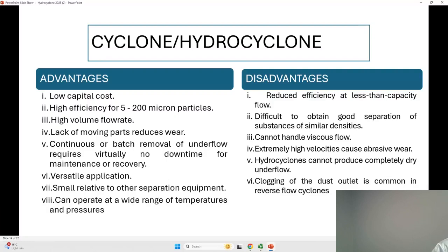example. You understand? I'm just looking at a point where cut point size is more or less like the point that separates lower particles from larger particles. So when you are dealing with larger particles, you want more of larger particles in your operation, it means you will order a hydrocyclone with higher cut point size.